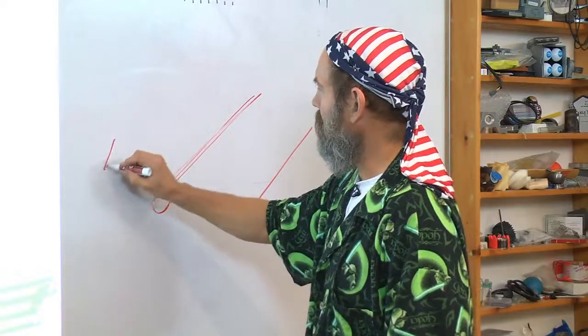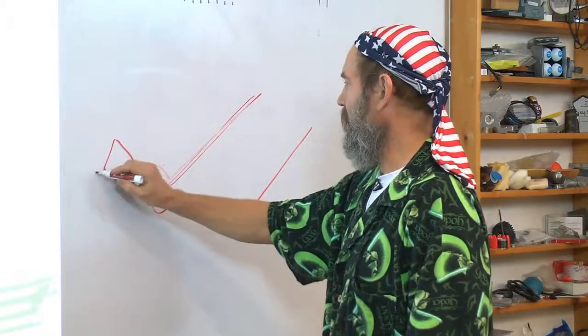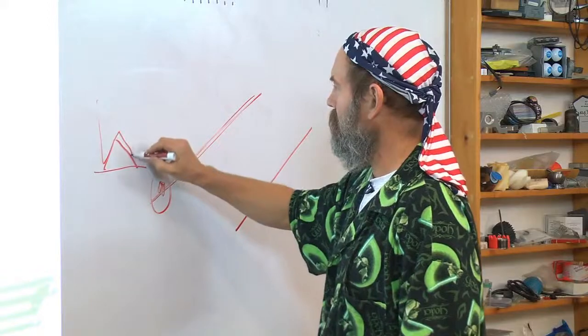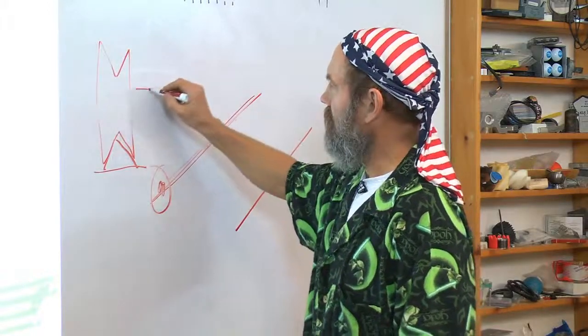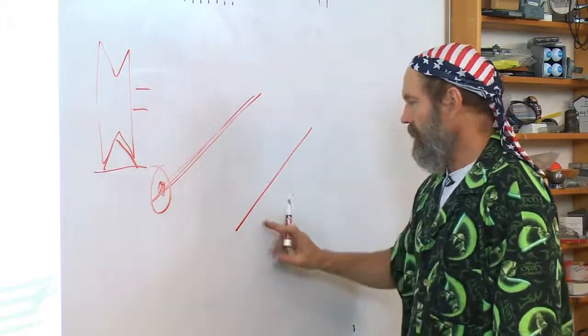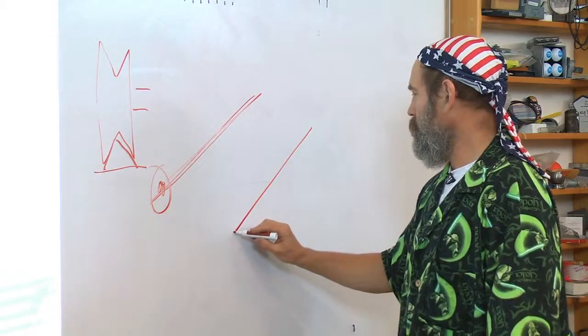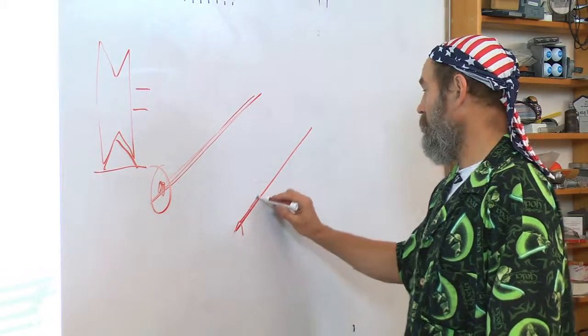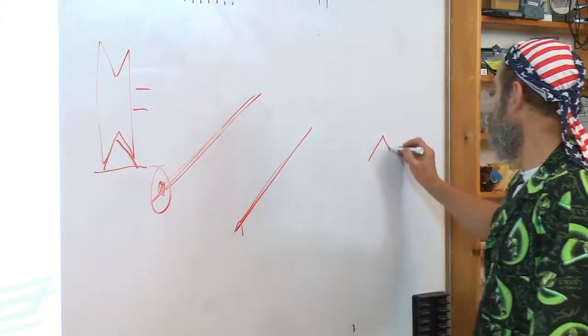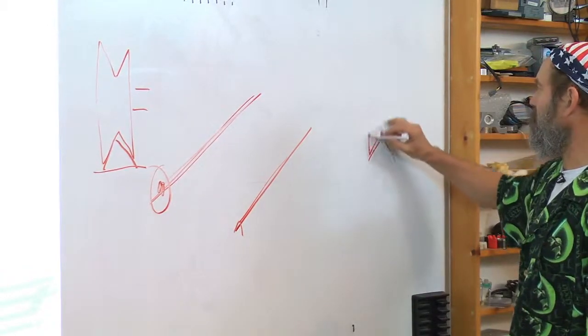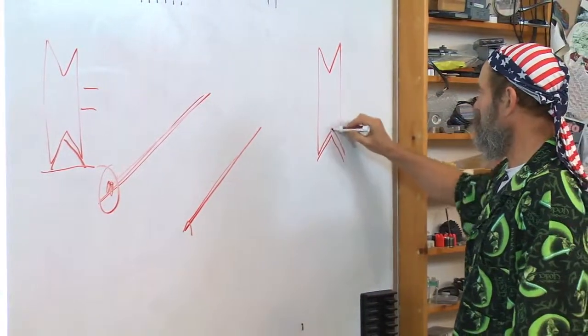If I draw this up, I'll have something like a piece of angled steel I'll lay down and a V wheel, shaft going through it. And over on the other side, am I going to put another angled bar with another V wheel on it? There are other designs we can do that are different than this, but we'll just pick this for now.